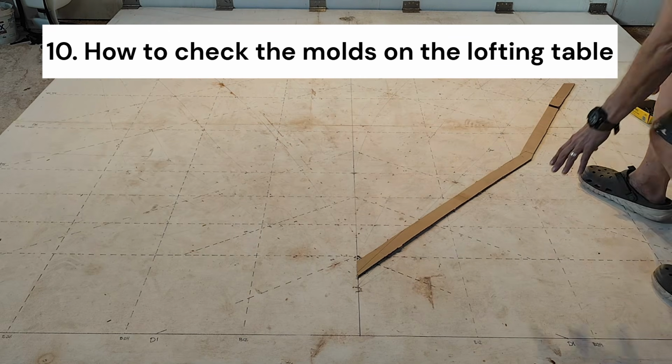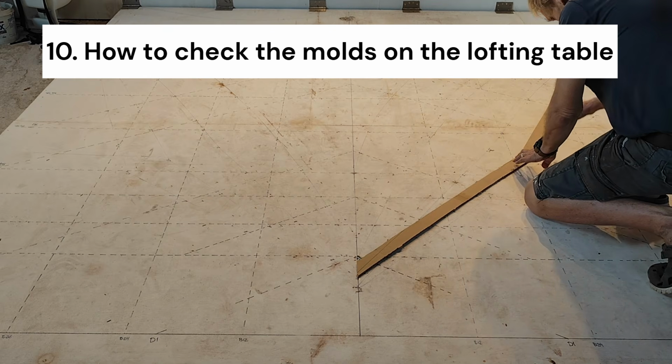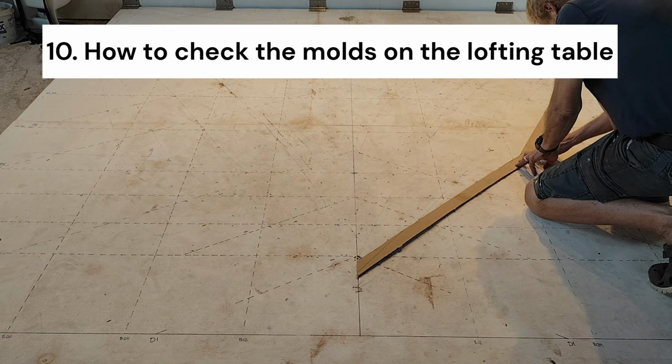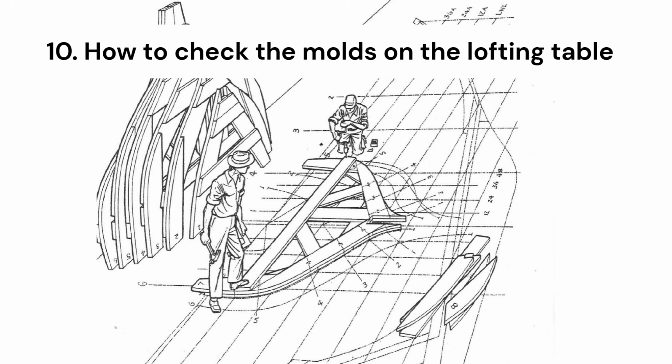10. How to check the molds on the lofting table. Take the mold and place it on top of the markings. Check if there is any mistake. If so, make a mark on the cardboard molds for adjustment. If your build is molds on a keel, also check like this picture from Bud McIntosh. If not satisfying, mark out with a sign and maybe some words what must be changed.